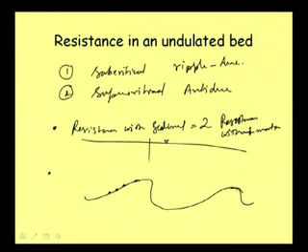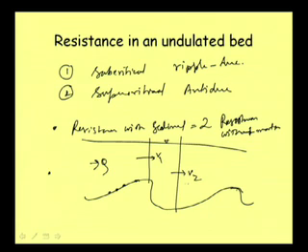As we can see here, suppose the flow is coming with a velocity v1, in this portion the velocity will gradually drop to v2. If the discharge q is the same, then it is dropping. Then it is a case of the velocity suddenly dropping, and due to this expansion of the flow, we can find how the energy gets lost. That loss of energy means some energy gets consumed in overcoming this sort of situation.